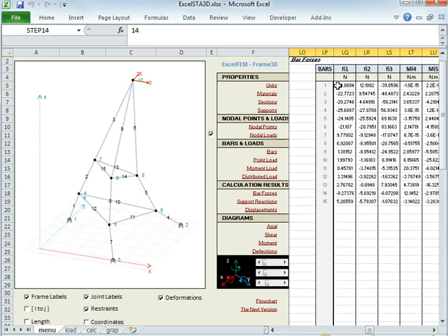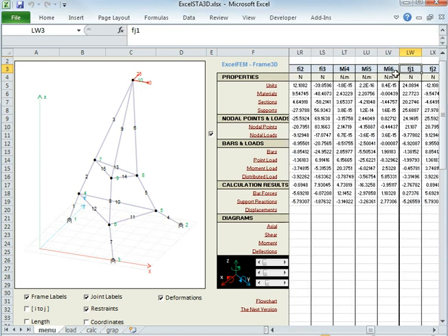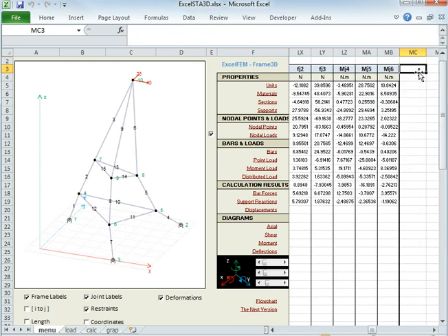So we can look at the element forces. So if we look at element 1, there's 2 nodes, and each node there's 6 forces, 3 x, y, z, fx, fy, fz, and 3 moments, mx, my, and mz. And you've got the same at the top. So there's 12 parameters for every single element here. So here we go. These are the forces in newtons, moments in newton millimeters for the first node, and then for the second we have forces and moments again.